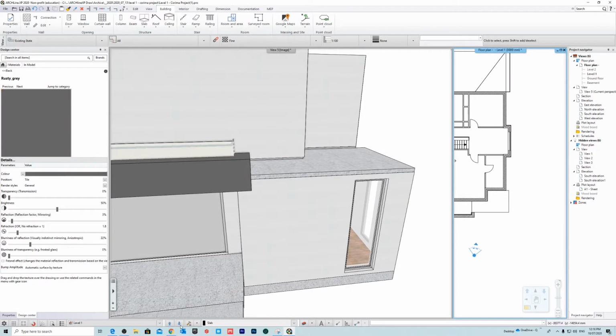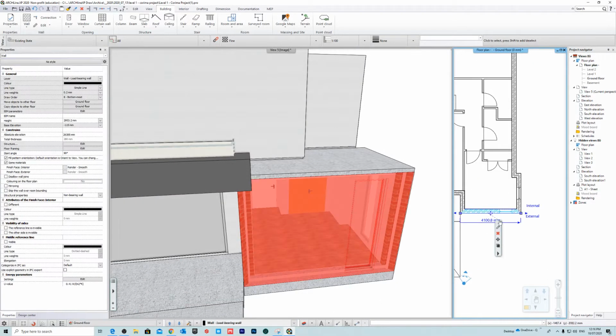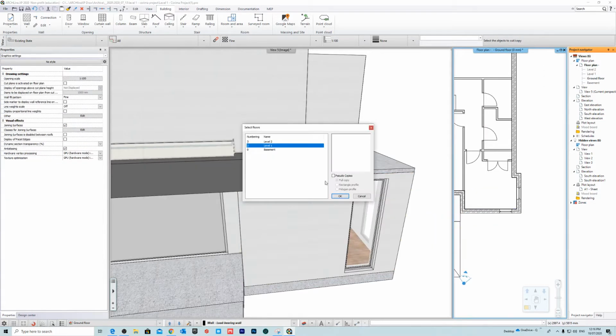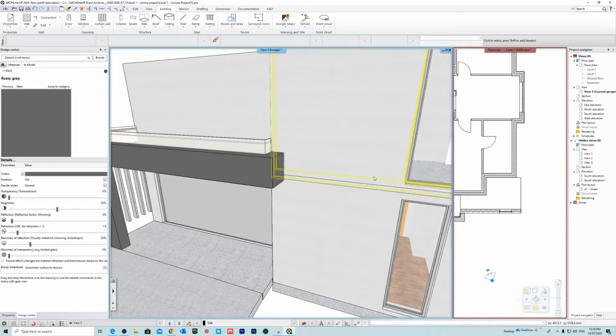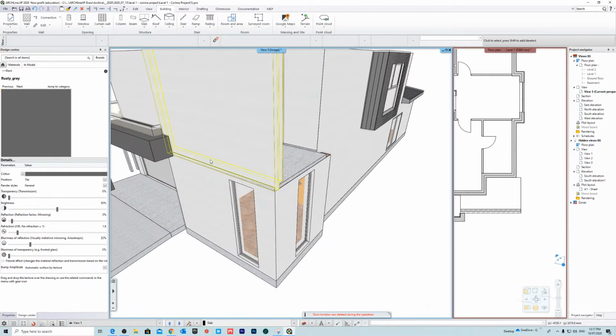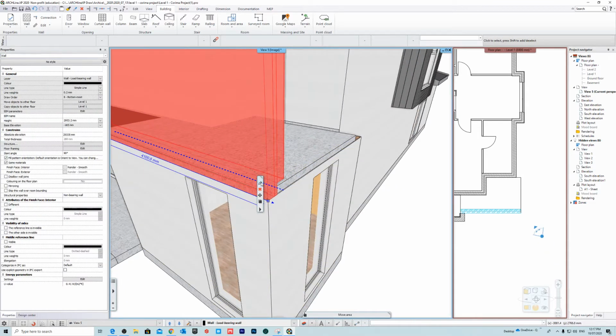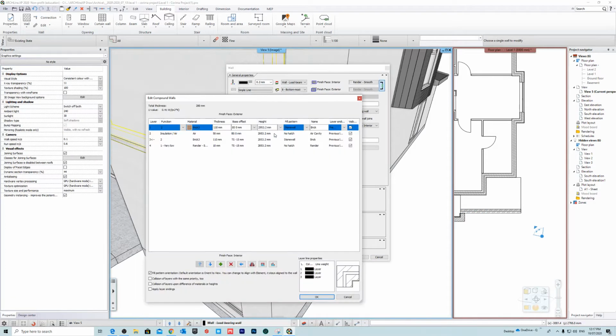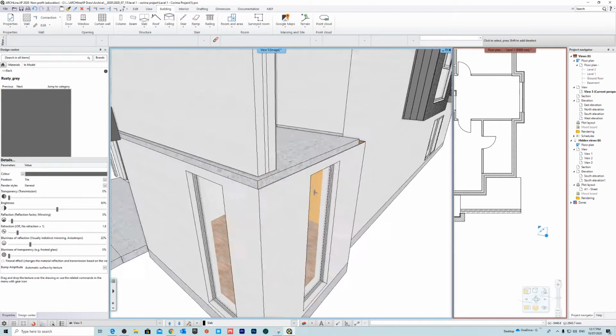Actually, we'll go back again, click on this, and go floor plan, copy objects, level 1. We'll delete this. We'll make this bottom of structure, and we'll make that top of structure. For bottom of structure, we'll go TS minus 15. So we want that to be sitting right on top. So go okay.